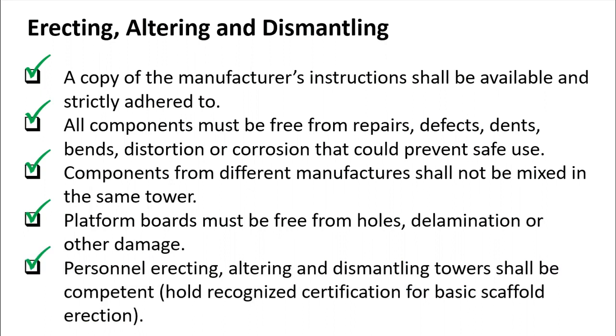Personnel erecting, altering, and dismantling towers shall be competent. So make sure that the persons engaged in the scaffolding works, scaffolding towers, are competent. Competent means that they hold recognized certification from the authority on basic scaffold erection, alteration, and dismantling.